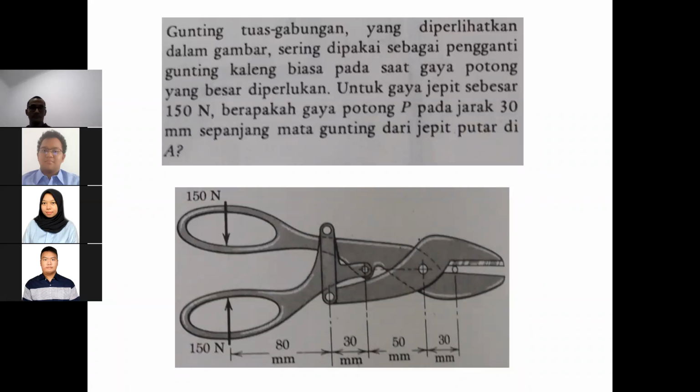Maybe the middle section. You mean this one? Yes, sir. Yep, correct. That one is two force member. So remember, that one is two force member. So we do not need to draw the free body diagram of that one. And we know the line of action of the force at the pin here and here, due to that particular member, we know already the direction.